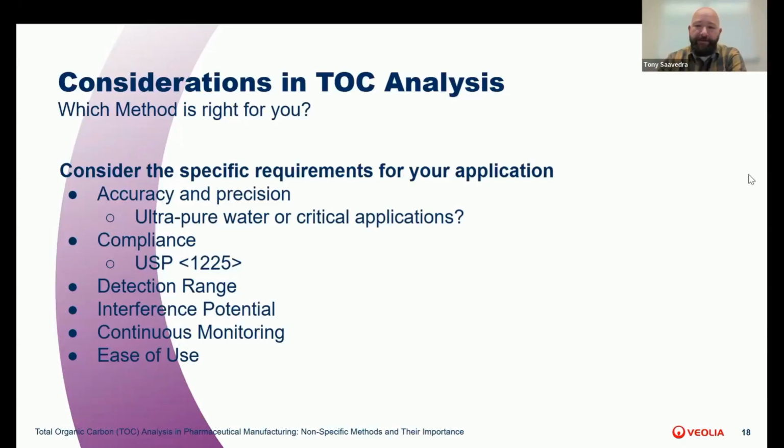In many pharmaceutical settings, you might end up using a combination of methods. For example, you might use direct conductometric for continuous monitoring, but then periodically verify with membrane conductometric or NDIR methods. At the end of the day, the right choice really depends on your specific applications, what regulations you need to meet, and your operational constraints. In my advice, always consult with analytical experts and really think about your unique needs when making this decision.